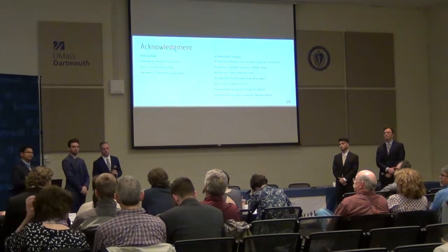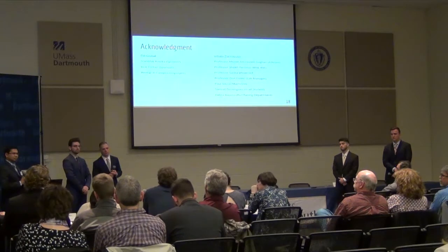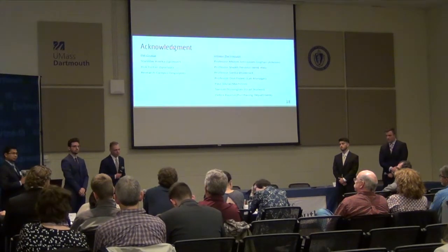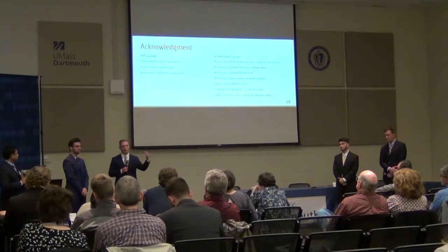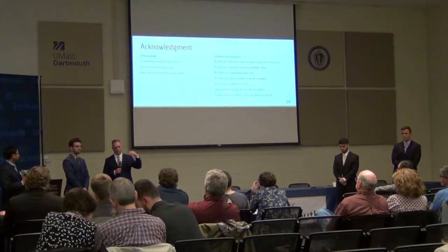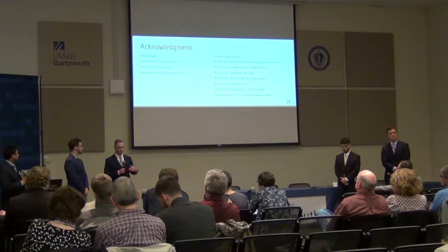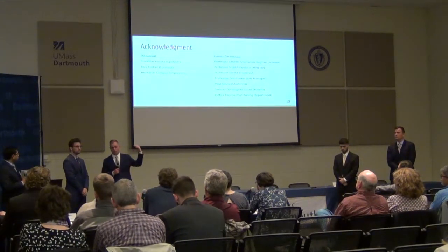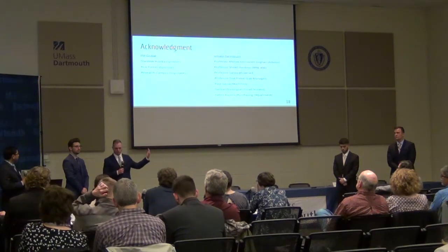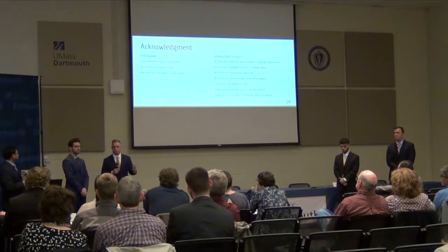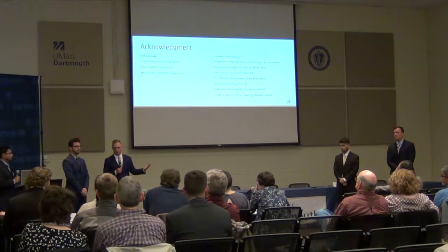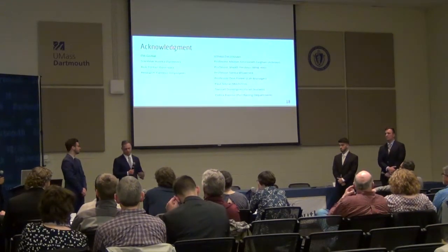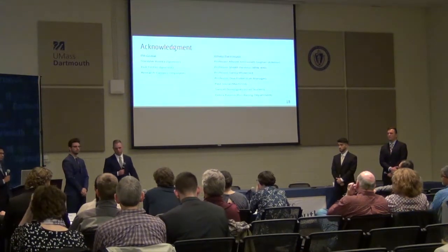If your maximum temperature goal was 2,500 degrees, why select a material that was only good to 2,000? Okay, so that maximum temperature is the worst case scenario. They have only had it reach that maybe twice ever, so that was way over the top. And if it even does reach 2,500, it's only for like 10 minutes or a short amount of time. So that's the worst case scenario. It should be able to survive, since we have stainless steel that's good up to 2,000 degrees.